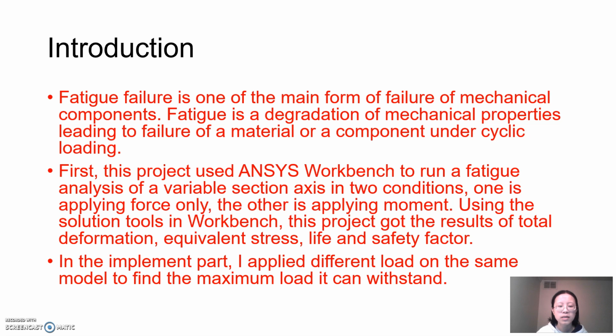Using the solution tools in Workbench, this project got the results of total deformation, equivalent stress, life, and safety factors. We can use the equivalent stress and life and the data from Workbench to calculate the stress safety factors. In the implement part, I applied different loads on the same model to find the maximum load it can withstand.